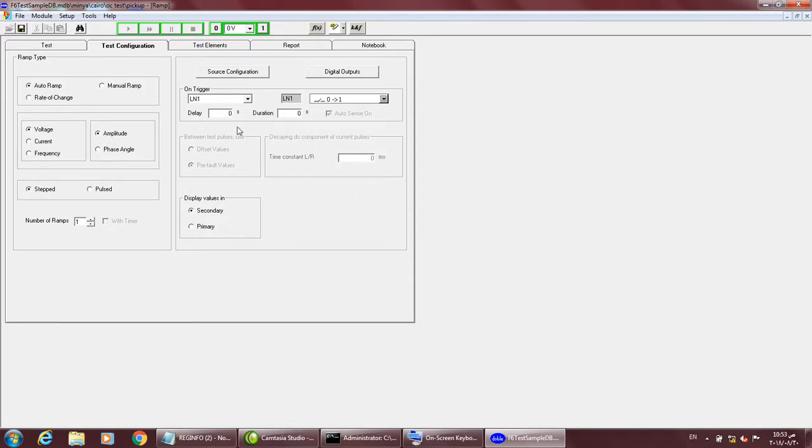Suppose you want this input contact to sense with a delay after tripping, due to some configuration in the annunciator where we need to hold it. If we use the relay, it gives a pulse, and the contact changes from NO to NC and again changes back immediately, like fuse fail. Suppose you have given a fault; the relay gives the trip command and it is just a command, and again it goes down.